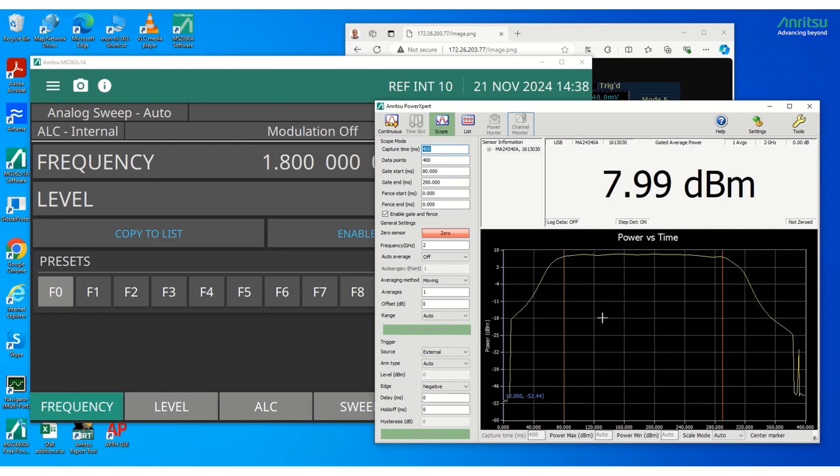That's due to the cable between the Rubidium RF output and the DUT input, which is the band pass filter input. And then the filter itself has got some loss. So put together, I think there is 2 dB loss between them, and you can see the pass band output power measurement of 8 dBm.